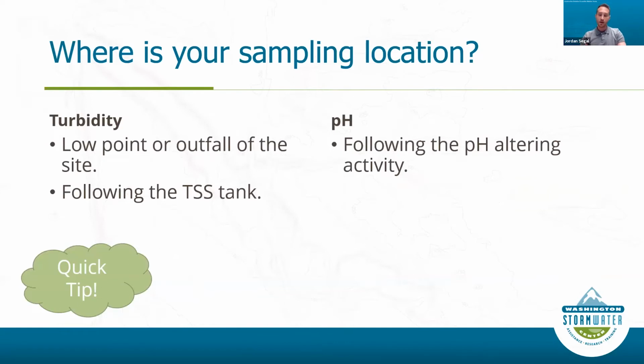Sometimes if there is a spill on the road or at another site, we need to trace that back. And if the pH isn't at the right level for aquatic life, and if turbidity is too high, which in our jurisdiction is over 25 NTUs, which is the measurement for turbidity, we're going to be imposing that changes need to be made or met, or those economic fines could find themselves at the project site, which will eventually trickle not just down, but will trickle up as if it's not designed properly.